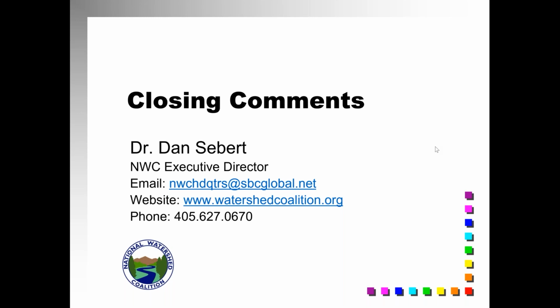Yeah. Just as a side note, I wish I would have put a couple of slides in on this topic. Animal guards are very important as well on these drain pipes. There are cases where they've actually found a dead beaver 100 feet inside the tow drain pipe where they've crawled in, and other animals as well. So animal guards are important on the entrances of these drains.